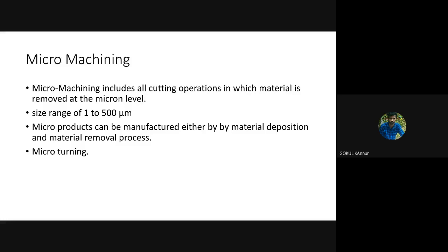How close can we machine to 50, whether it is 50.00001 or 49.9999, something like that? If it is like that, we can say it is more accurate. If the value goes beyond the limit, then we can say the accuracy is lost. So that is the accuracy, the closeness to the true value.